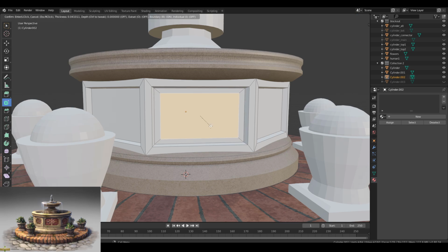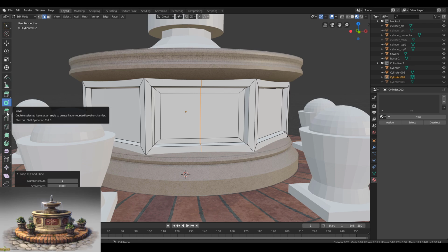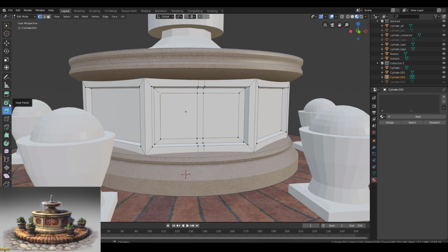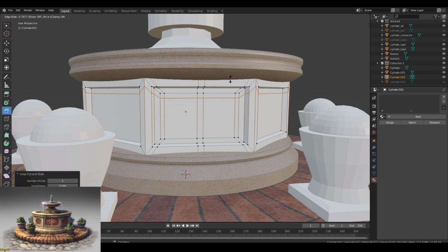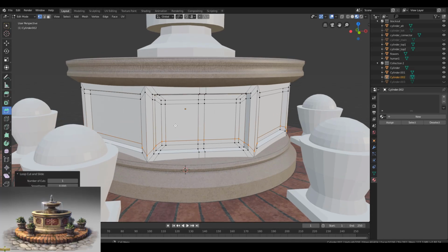To do this, I use the Inset option of the front wall, split it in two, and use the Bevel option on the newly created edge. Now I added additional edges to make another recess in the wall and then smooth out the sharp edges using the Bevel option.